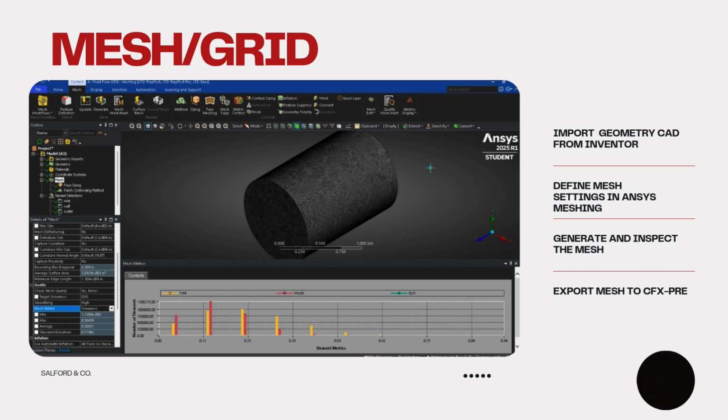We used finer mesh elements near the ball surface and added inflation layers to accurately capture boundary layer effects. The outer domain was meshed more coarsely to save computation time. Mesh quality was checked to ensure good skewness and orthogonal values. In total, our mesh contained around 500,000 to 2 million elements, providing a balance between accuracy and efficiency.